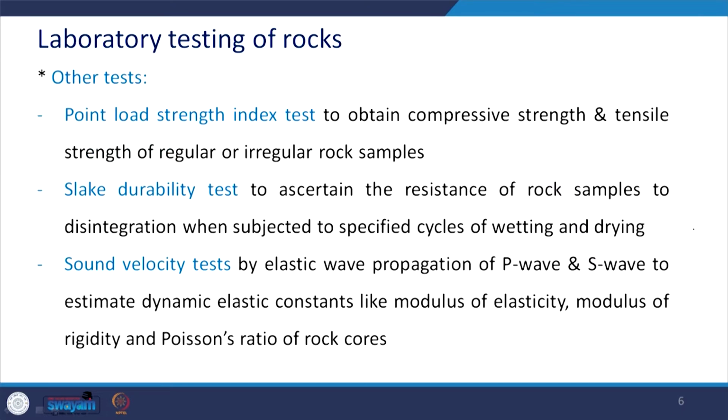Some of the other tests apart from these include the point load strength index test. So, apart from the unconfined compression tests, this test also gives me an idea about the compressive strength and also the tensile strength of regular or irregular rock samples.